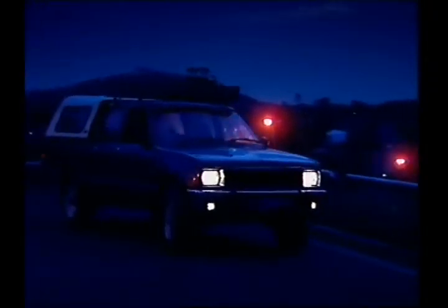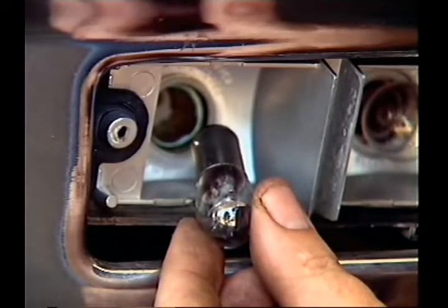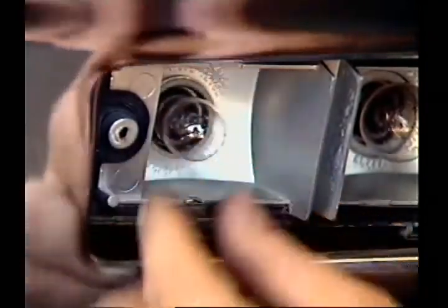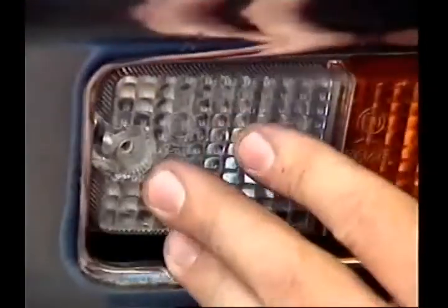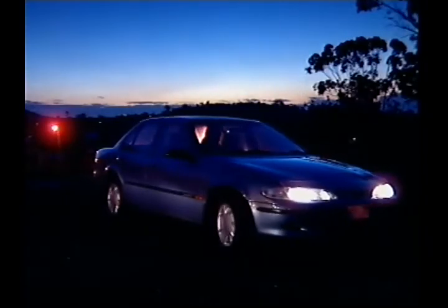The park lights, sometimes called clearance lamps, are located at the front of the vehicle and are used at night time when the vehicle is parked on the side of the road. They use low wattage bulbs and may have a lens or diffuser that makes the emitted light widespread. In some cases, the park lights are incorporated in the headlight assembly.